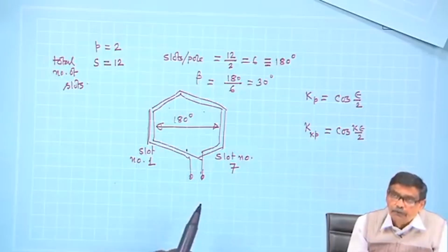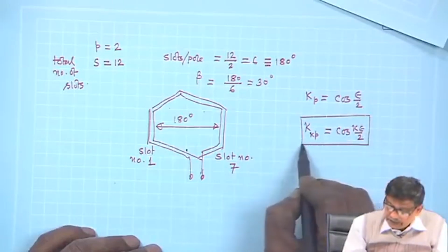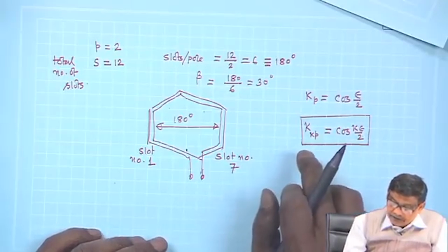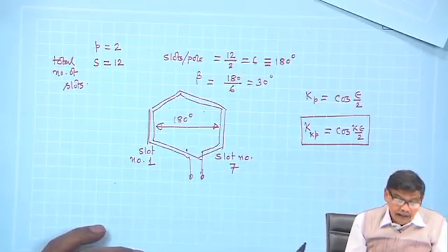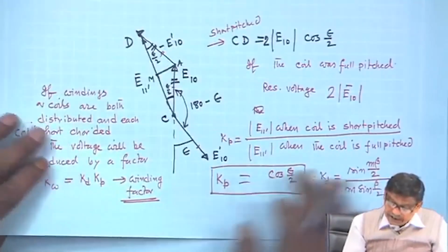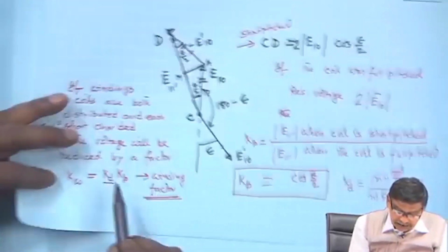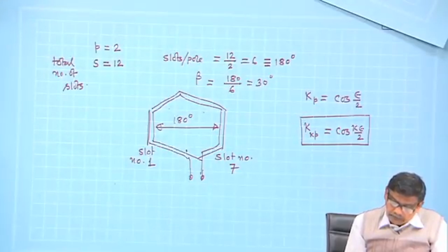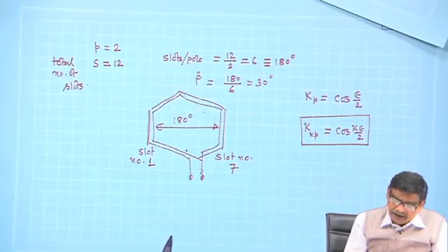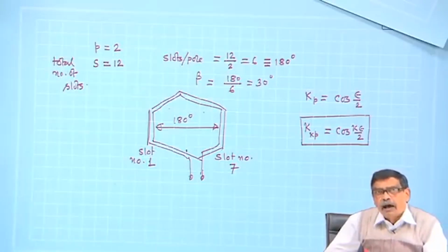Electrically it will be much more now. Therefore, this is the pitch factor for kth harmonic. Is that clear? And in the expression of the EMF, net EMF across the coil, it should be multiplied with both Kd and Kp. So, suppose I know that there is third harmonic, fifth harmonic, and I decide that I will try to eliminate the third harmonic voltage.